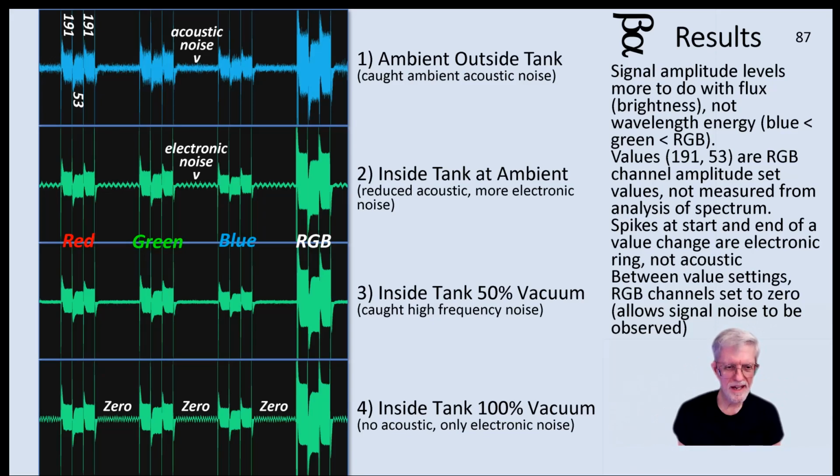So it picked up that noise. That's acoustic noise. And then inside the tank at normal pressure, you can see that little wiggly wave, but you don't see the blur, because inside the tank with the lid on, even not under pressure, it removed the acoustic noise, and now all it had was electronic noise. This is the signal to noise ratio of the microphone circuit, because I've amplified it to see that. I wanted to see what was there.